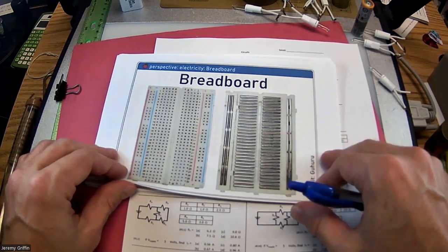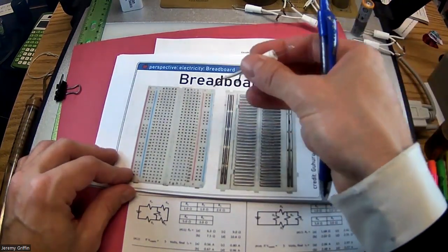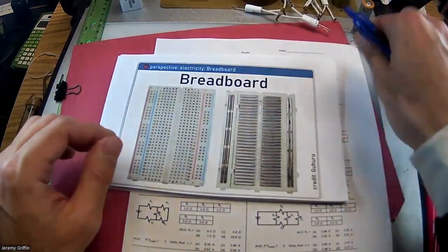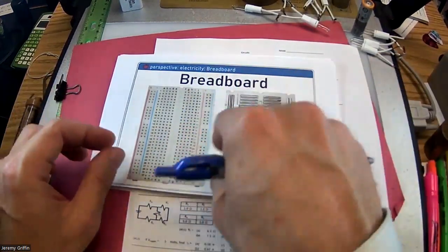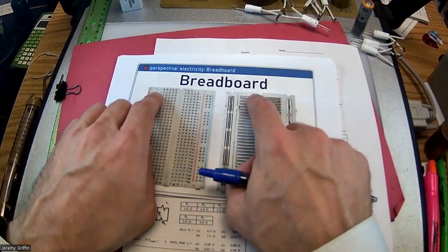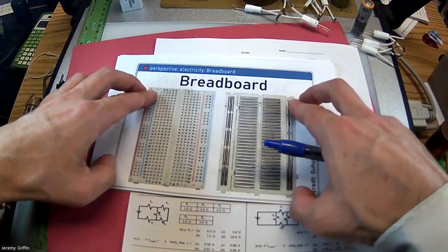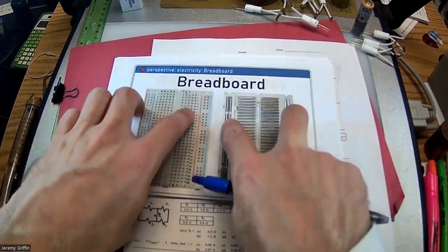Right, breadboard, so you can plug in resistors and voltage sources, and also capacitors and inductors, and make all different things. I've seen people build little mini robots out of these, if you know how to wire stuff up. Now, what's good to know is how everything's wired on the backside. Like these 5 are connected, these 5 are connected. There are also rails or buses that run along the entire outside here.